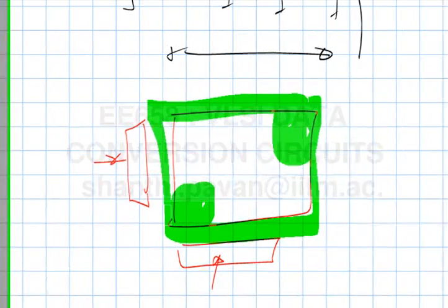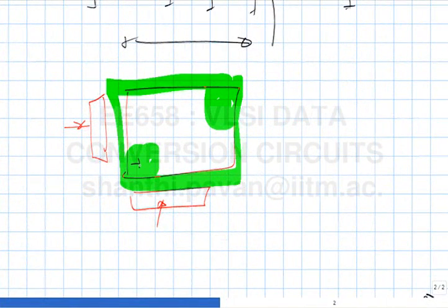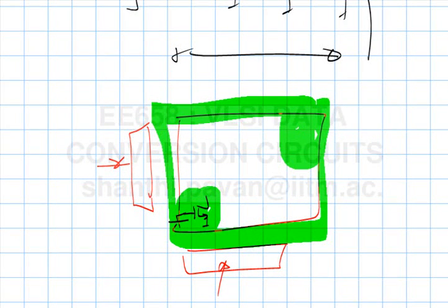Do you understand the problem? The problem is that if I had a transistor here and generated VGS, some bias voltage, and I apply the same bias voltage to a nominally identical transistor here, the current will be different because the Vt is slightly different. Please note that this is a systematic variation. I am not talking here about random mismatch. So if I did this for 10 transistors in this area, the average of their currents will be much higher than the average of currents of 10 transistors, say somewhere here and there.